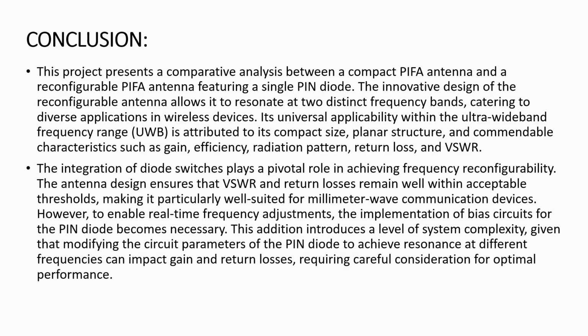Coming to the conclusion, a comparison between a compact PIFA antenna and a reconfigurable PIFA antenna with a single diode is presented in this presentation. The presented structure functions with a single PN diode that resonates at two different frequency ranges suitable for various wireless device applications. To attain frequency reconfigurability, the introduction of the diode switches proves instrumental. The designed antenna exhibits VSWR and return losses well within the acceptable limits.